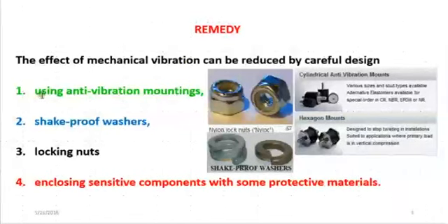We said there is need of using anti-vibration mountings, and one of the students required that I should show them samples. Here are typical diagrams of anti-vibration mounts. You can see that at the two ends they are made of metallic substance, but in between we have rubber, which, when it experiences any mechanical compression, will vibrate in such a way that it absorbs the effect without letting it propagate into the system where the component could be harmed.